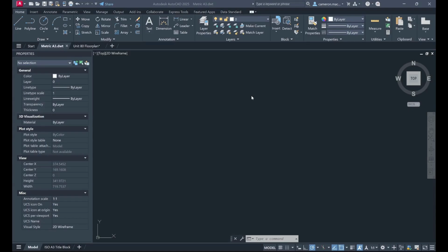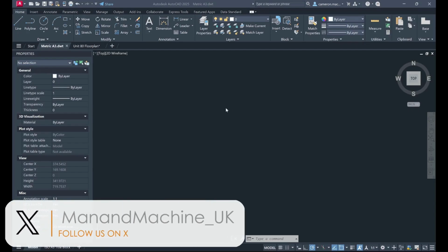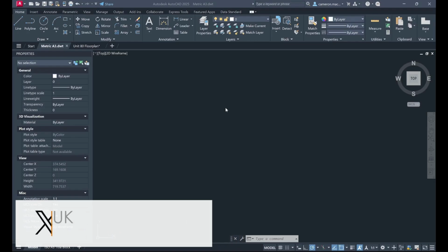If we decided that we want to make use of our template files and set a standard based on that template file, this doesn't have to be a template, this can be a drawing file as well, but we can start to use some of the information that is sat inside of this and start to drive any others going forward. So to do this, we can essentially take any layers and dimension styles and text styles and a few other variations in standards and styles within the drawings and begin to force these or apply these to any